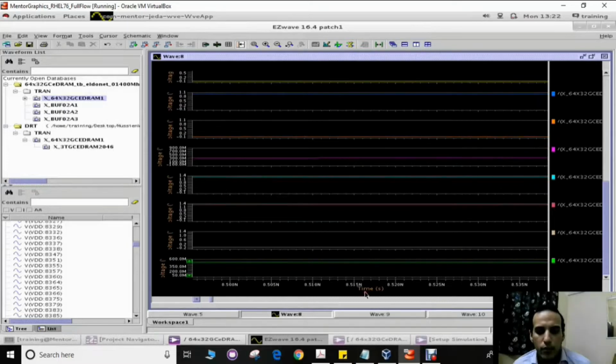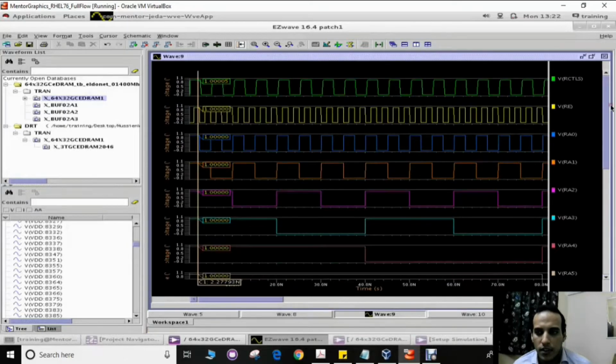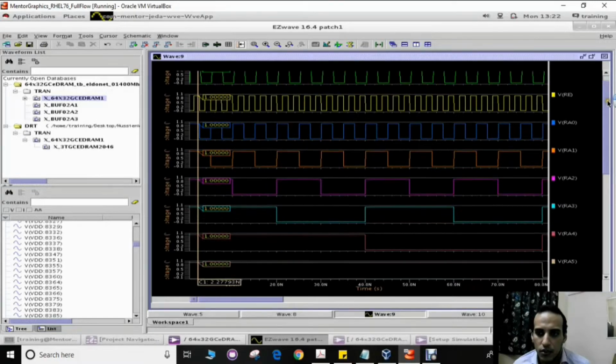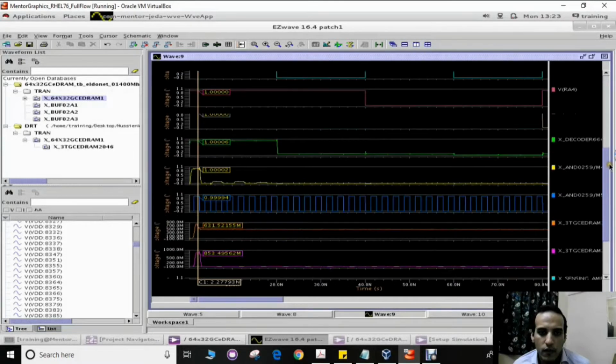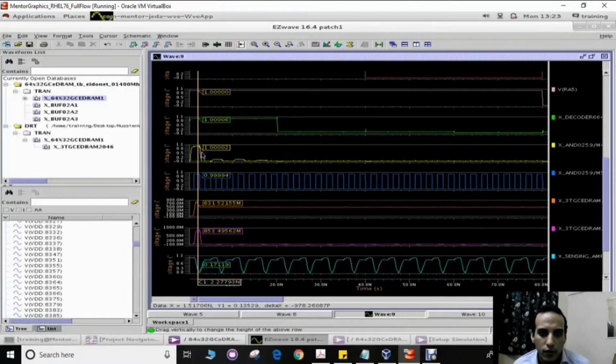For the read operation, the same procedure will take place, where first the read clock signal and the read enable signal will turn on the read decoder, and the output of the read decoder will turn on the read word line driver circuit after meeting the global clock signal. As we can see, the storage node still contains 1, and the read word line is high.